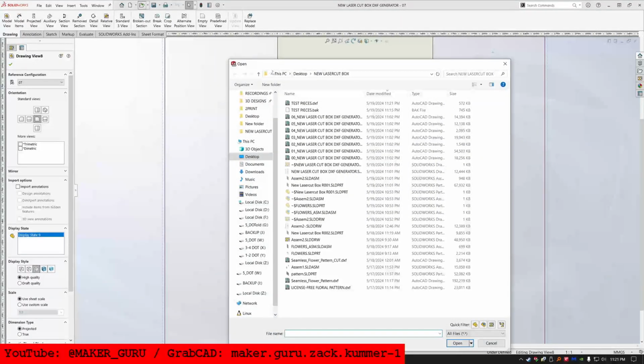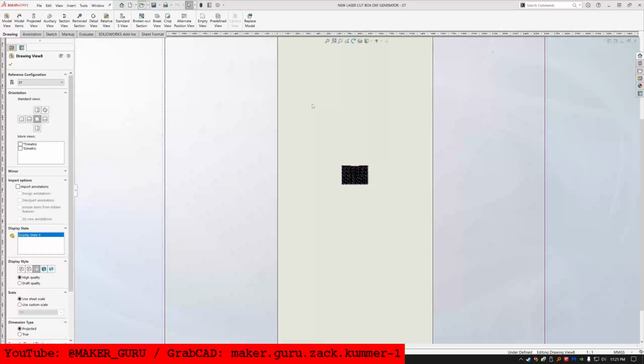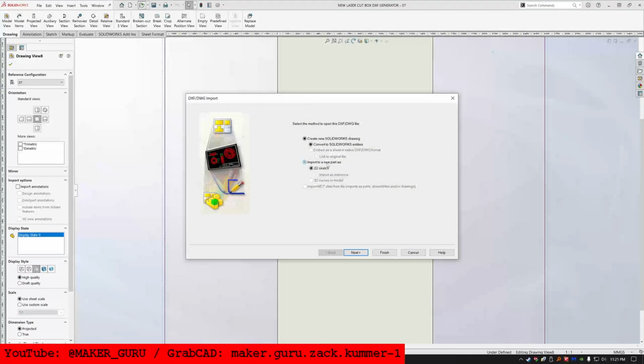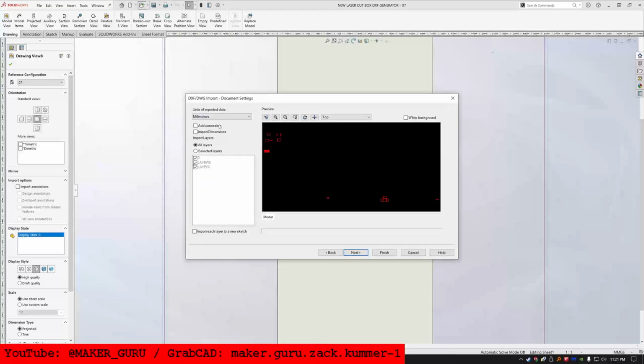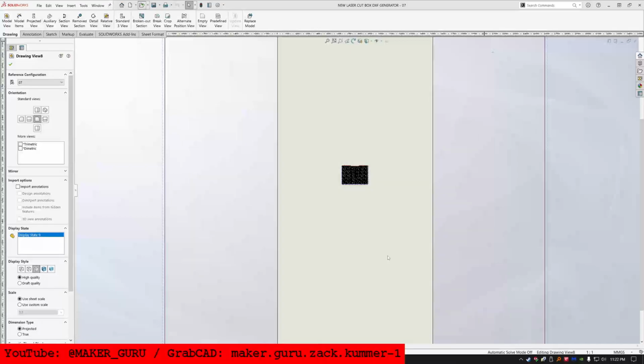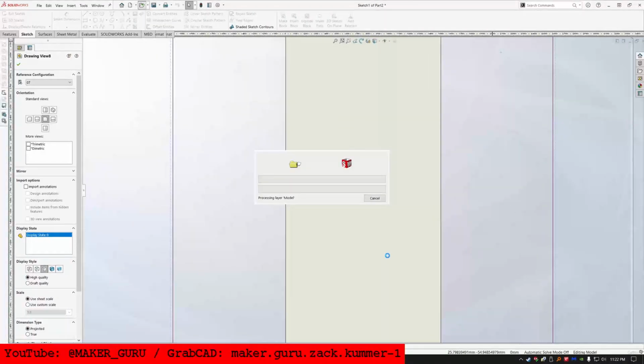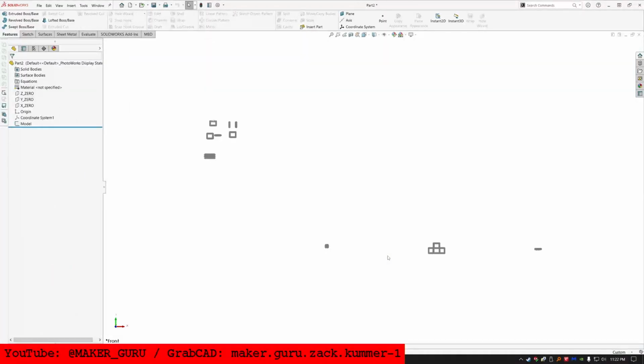Last thing I want to do is make sure this thing actually goes together. So I took all the actual cut lines from all the exports, put them all into one, and then I offset them equal to the kerf offset, so they should fit together very nicely.